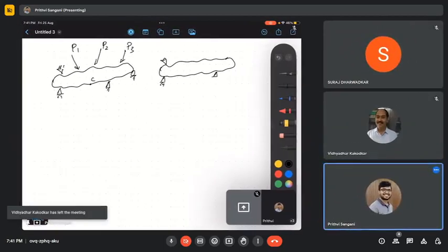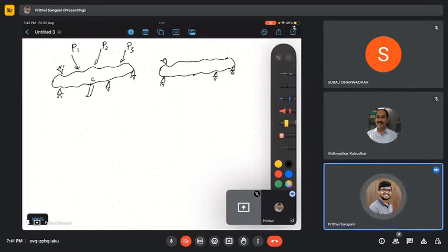Instead, the point where we are interested to find the displacement, right? Let us say that the point is C. This point, we want to find displacement in this direction. Let us say this direction delta. So we'll apply a unit load, that is one. Then we'll find out the internal reactions, let us say internal reactions U. Internal reactions are nothing but, for the truss, the internal forces. For the beam it will be the bending moment and the shear forces.